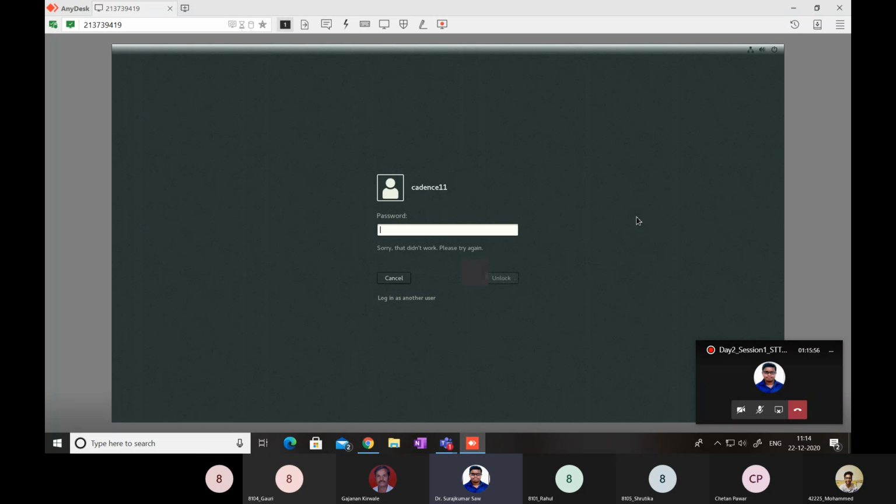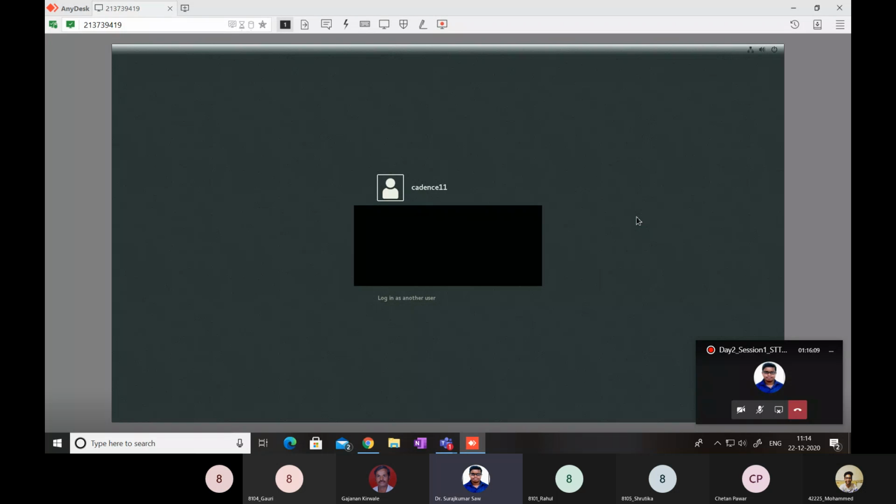Now you see, one more thing I want to tell you. These are the outputs you have selected. Sir, I'm getting an error. Okay, wait, I am coming one by one. Your output has come, but it is deteriorated. Mohammed, you just check it. I hope you have not provided the supply voltage. I have to check it once. You have provided supply voltage Z. You have not given the supply voltage. Without supply voltage, the circuit will not run. You have to provide the supply voltage here.